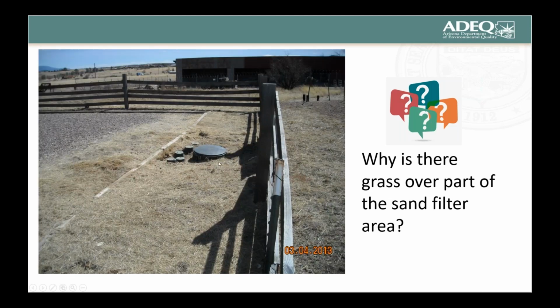This is the same facility. It's a recirculating sand filter. This is the sand bed here. This is a rotating valve that shifts every time the system is pressurized to distribute effluent in the gravel bed. This thing ratchets up and routes it through one flow zone after another, and these are the shutoff valves for the different flow zones.